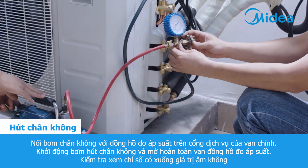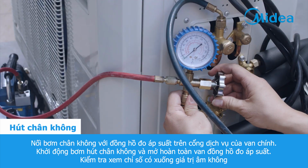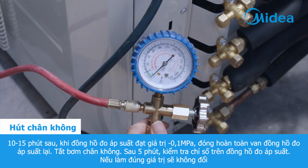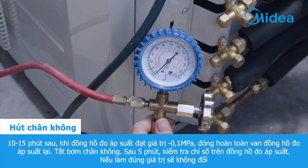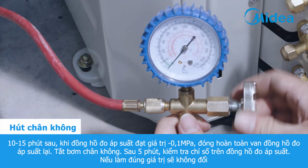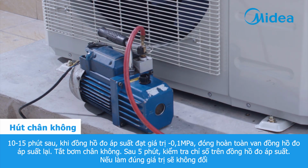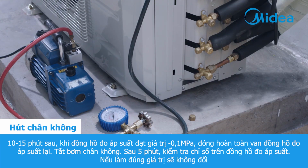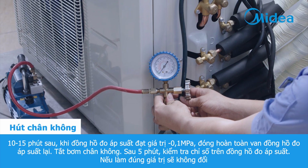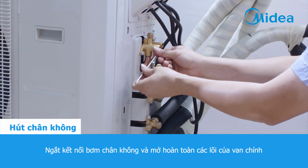Start the pump to vacuum and fully open the valve of pressure gauge. Check if the reading goes down to negative value. 10 to 15 minutes later, when pressure gauge reading is minus 0.1 megapascals, fully close the valve of pressure gauge. Turn off the vacuum pump. After 5 minutes, check the indicating of pressure gauge. It should have no change. Disconnect the vacuum pump and fully open the cores of master valves.